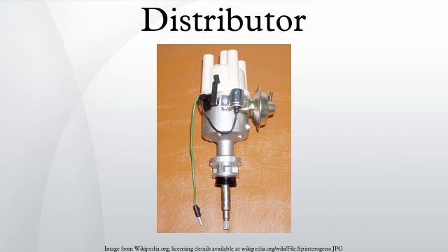the distributor can short out the electric current that should go through the spark plugs, rerouting it directly to the body of the vehicle. This in turn causes the engine to stop as the fuel is not ignited in the cylinders. This problem can be fixed by removing the distributor's cap and drying the cap, cam, rotor and the contacts by wiping with tissue paper or a clean rag, by blowing hot air on them, or using a moisture displacement spray, for example WD-40 or similar.